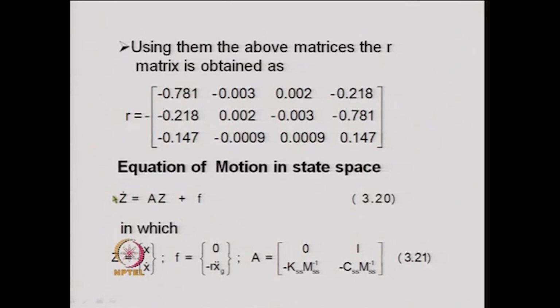In one case we are writing down the equation of motion in terms of the relative displacement, and in the other case we had the equation of motion in terms of the total displacement, and on the right hand side we had a KSG matrix and we require ground displacements instead of ground acceleration. Those two multi degree of freedom second order differential equations can be written in the state space form as before.